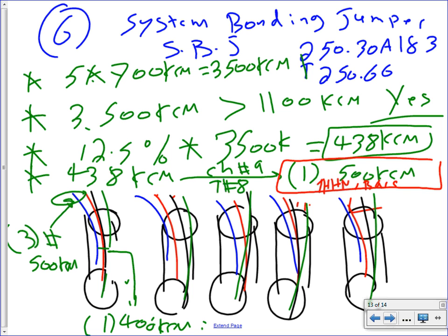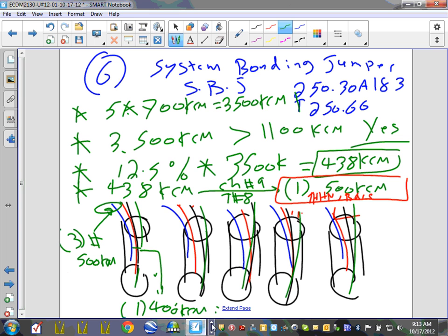Yes, sir. The 600 mil area only goes up to 211 kcm. Flip to the other side, to column one, the same table. Yeah, the first column becomes the kcm. After 4 aught, they start sizing in kcm. Make sense? You can't believe how many times I get asked this question, Aaron, you're not alone. 500 kcm doesn't have how many kcms in it, because it's already in kcm. No problem. Okay, so let's go, guys.